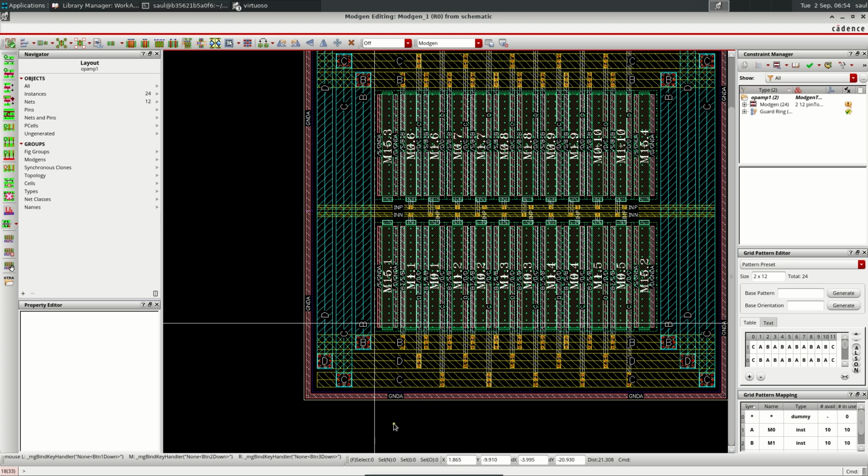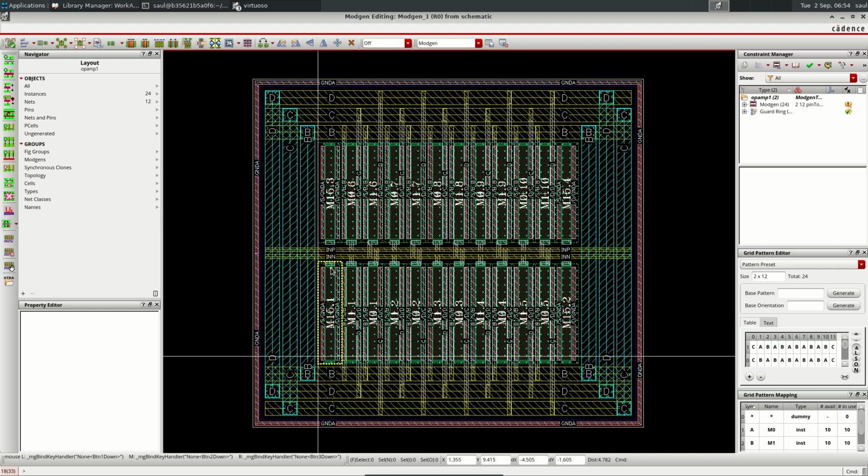and yeah, I will defer the connection of the source and drain and gate of the dummies to the layout, when I'm connecting all the modules together, because it's a little bit easier and it is very much quicker to do it there than try to use trunks for the connections here. That will add more parasitics. Okay, so